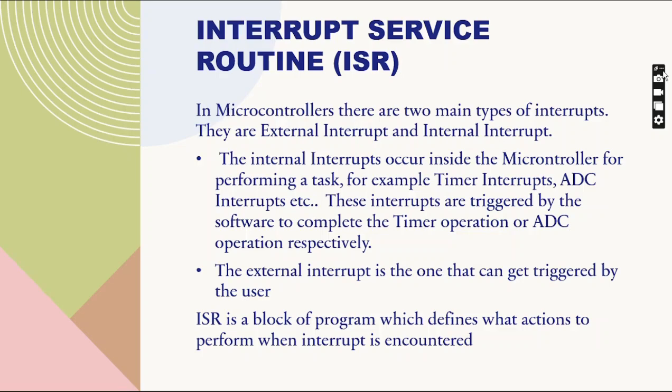Whenever the final count of the timer is reached, it creates an overflow. It sets the overflow flag, which causes the interrupt, and that interrupt is useful in programming, which we will see later. An external interrupt is caused by the external peripherals connected to the microcontroller. An interrupt service routine is a routine, basically a function, stored in the memory, which defines what the microcontroller should do if a specific interrupt is encountered.